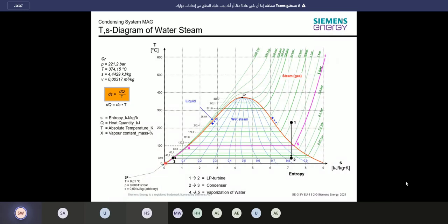So when we're getting here into the TS diagram, we're getting to our 100 degrees again. So at 100 degrees, we have here on the left side, 100% water. And now for the evaporation, the vaporizing of the water, we're giving more energy in, and we're getting now to this point, 0.1. So we have over here 10% steam, 90% water. So there are some bubbles in already. But the temperature is not getting down to 70. The temperature here is constant.